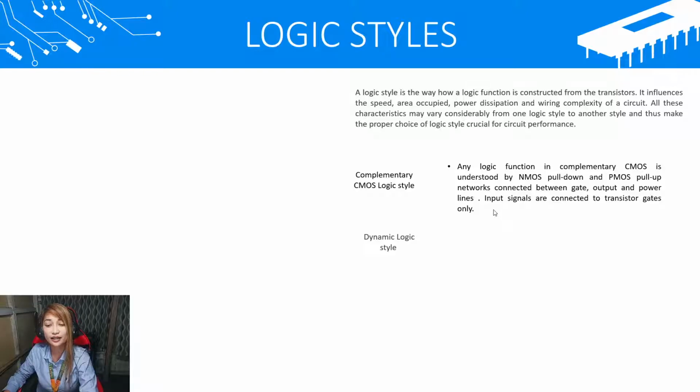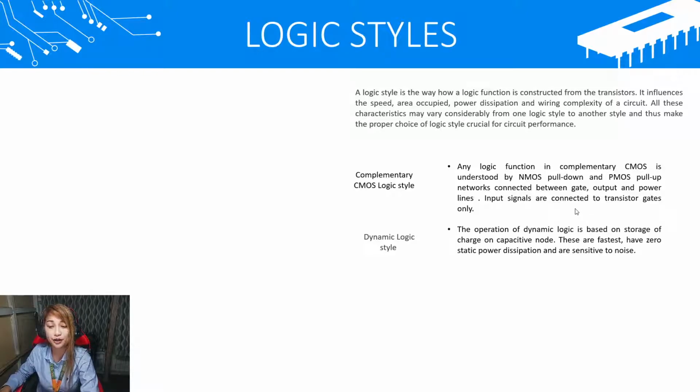Next, the dynamic logic style. The operation of dynamic logic is based on storage of charge on a capacitive node. These are the fastest, have zero static power dissipation, and are sensitive to noise. The domino and dual rail domino fall under this category.